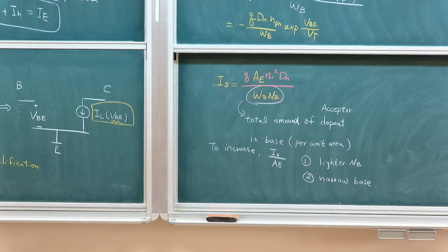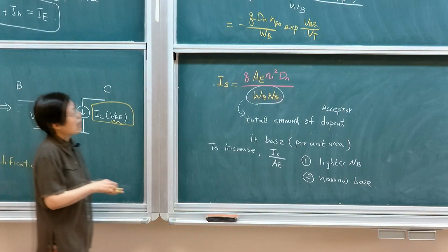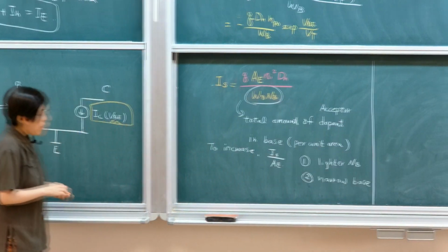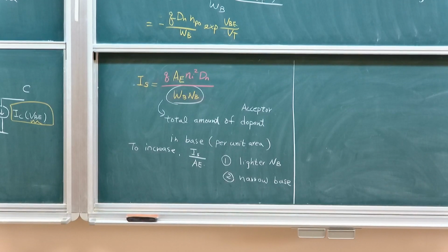So once we already know our collector current is the main current that we want to control, base current is like the price you pay for making the transistor active mode, for example. So it's like how much you need to pay to turn on the transistor. So the base is the part that we actually don't want to function because it does not contribute to output current, but it's the price you pay. So we need to talk about how you make the beta value of your transistor as high as possible. So cost, what is it?